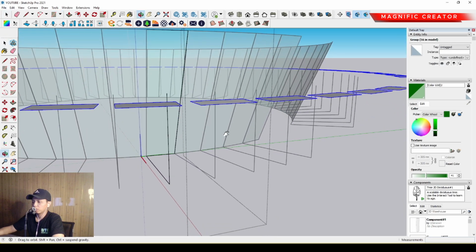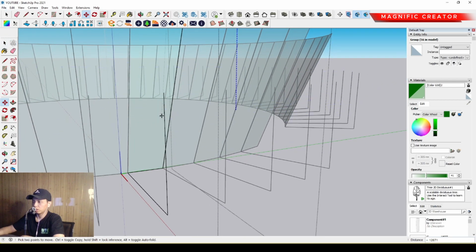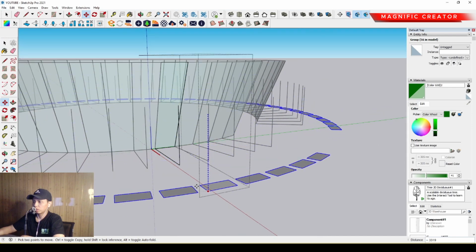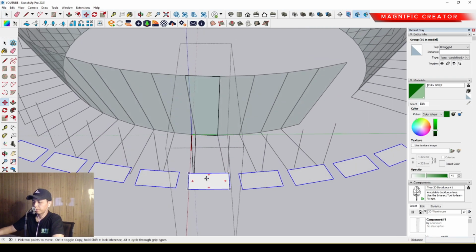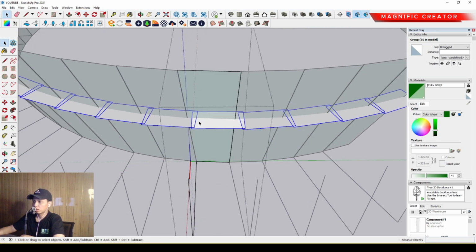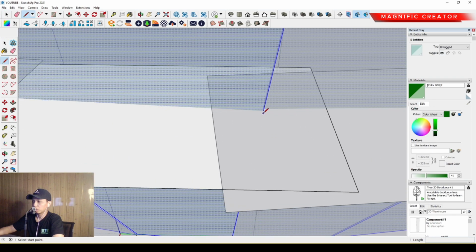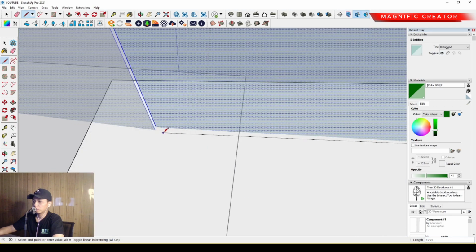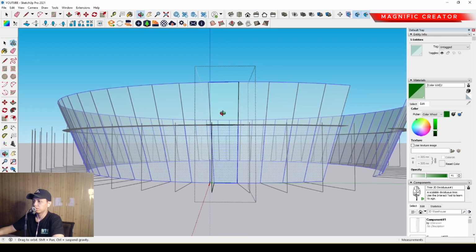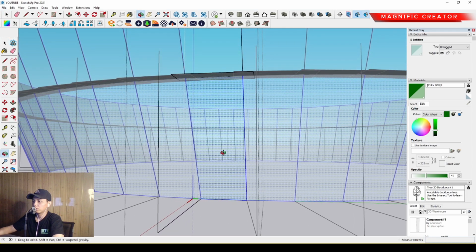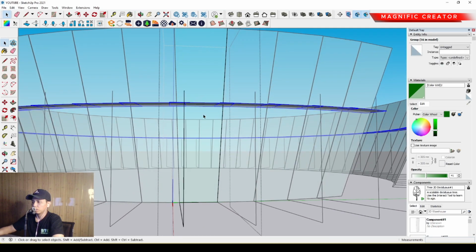frame divider anyway. We can set the frame height of the frame divider using this plane, and we can use this plane. We can move it to this area, so we can move it to intersect with this glass panel, so then we can make a line in this area. Okay, just like this, and we can move it again.